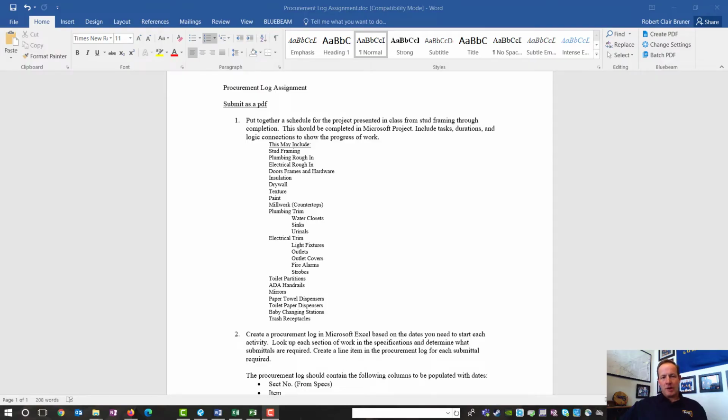Okay, I want to talk to you about your assignment now. And this assignment is a procurement log. And this is going to be a valuable tool for a superintendent. Being able to track and monitor all of the submittals to make sure that things are going to arrive on site and that contracts by the project manager are being written on time so that things can arrive on site. Because ultimately, the superintendent is responsible for getting that building built on time and keeping that schedule. And so understanding what a procurement log is, is critical for a superintendent.